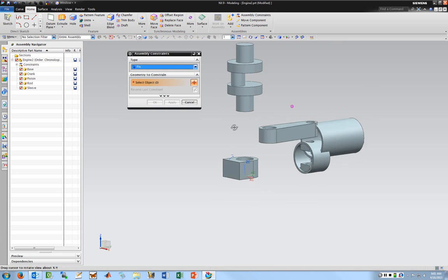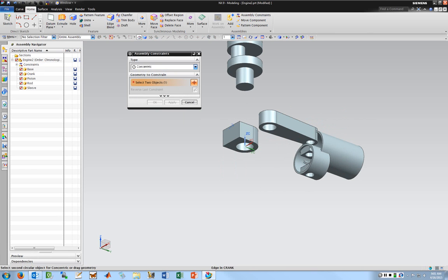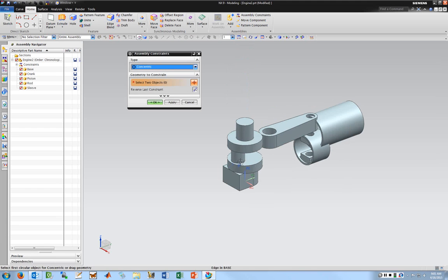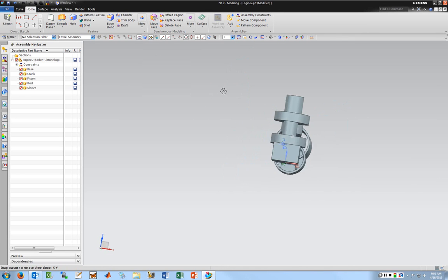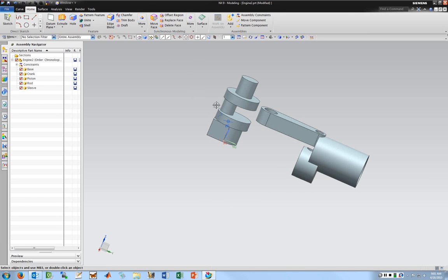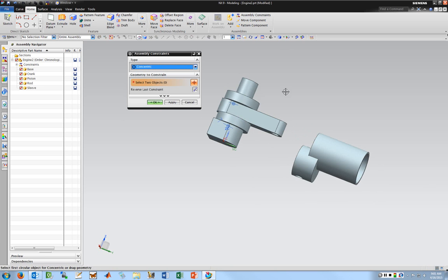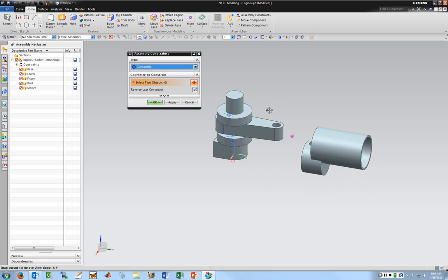And now I want to put the crankshaft in, so that's going to be a concentric, which will map over to the motion simulation just fine. Okay. I do want to go ahead, is that thing clocked correctly? Yeah, that's clocked correctly. So I don't need to rotate this. So what I do need to do is get the connecting rod in place, so that's going to be another assembly constraint, concentric. I'm going to pick that edge, and the connecting rod's where it's supposed to be, and it's in the right configuration. So this would be at bottom dead center for the engine.